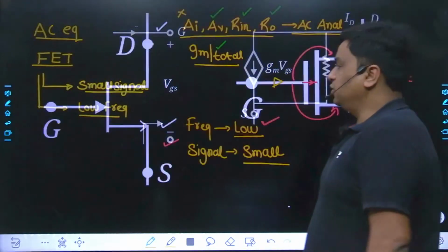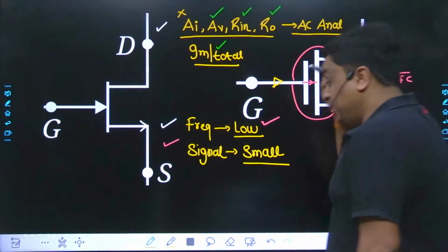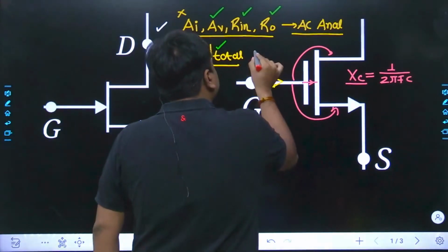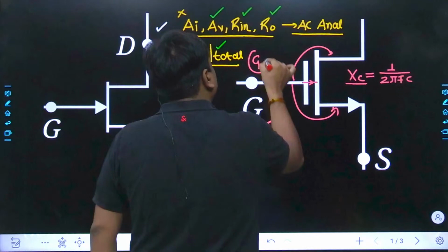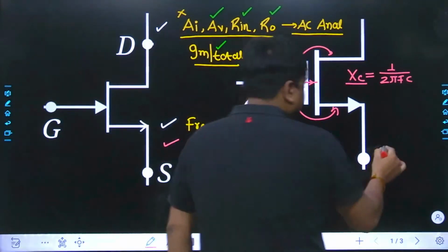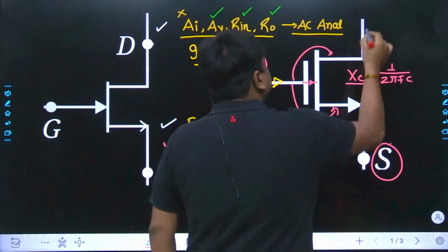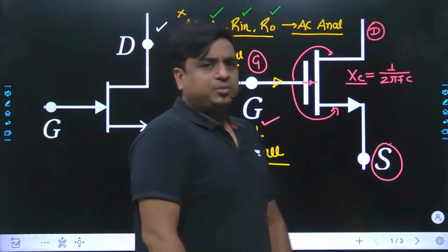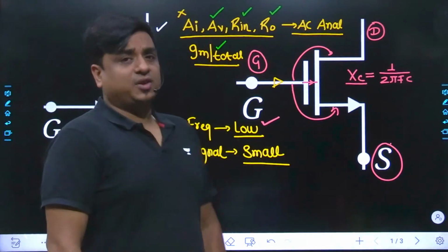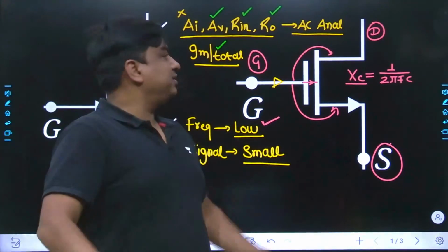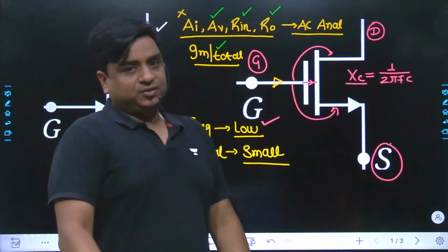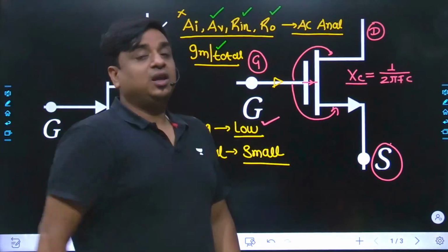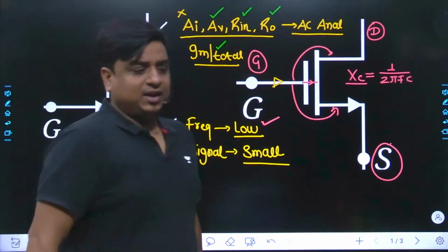What to do now? First you have to identify these three terminals. Obviously we have three terminals. The middlemost terminal is the gate. The terminal which carries the arrow is the source terminal, and its counterpart is the drain terminal. So virtually speaking, MOS has three terminals. Physically it has four terminals, but usually bulk or base is straight away short circuited with the source. So I used to say we have three terminals specifically in MOS, either it is an NMOS or a PMOS.